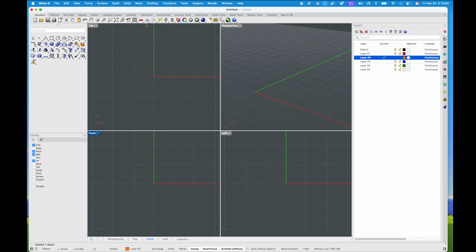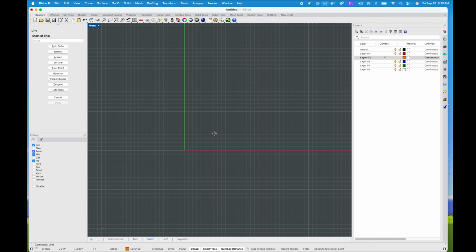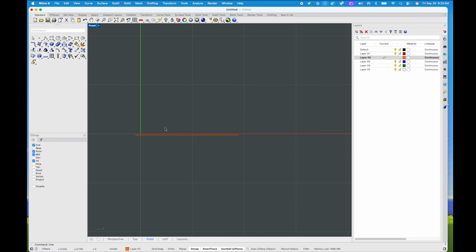We'll see that this view, and unfortunately you won't see me pointing to this in the screen recording, so you might want to pay attention a little bit. All right, basically we're going to draw this view and draw this view, and see if we can actually produce the other one. To be fair, we can use this just like we do drafting. So for instance, if I double click on my front view and I simply try to draw this object, well, I can do that in a multitude of ways. I can just draw some lines, right? Click, and I can type in 2 inches, enter, and you'll see that actually 2 inches is about that big.